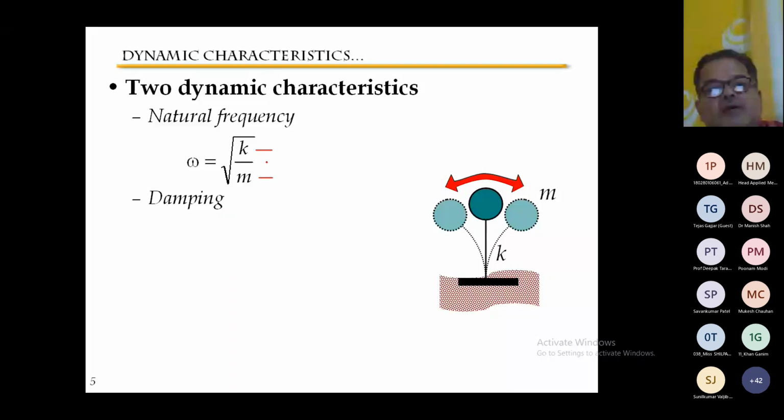So here, suppose a low frequency earthquake comes. If a low frequency earthquake comes, we know that the high-rise building has low frequency. So the earthquake will affect the high-rise building rather than the low-rise building. Suppose I assume it is a high frequency earthquake, or the earthquake contains high frequency, right? If the earthquake contains high frequency, then the low-rise building will be affected, right?